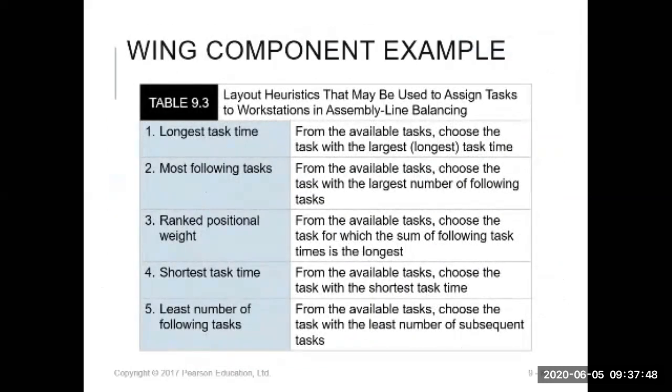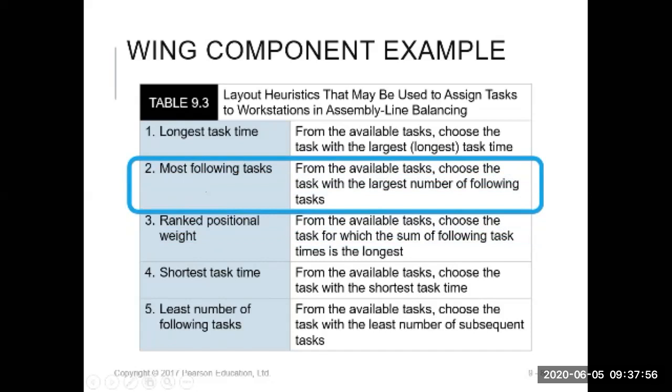Now we will assign. To assign the tasks to workstations, there are about 5 methods. But in this example, we will use only one rule, the name is most following task. So from the available tasks, choose the task with the largest number of following tasks. That is the rule.